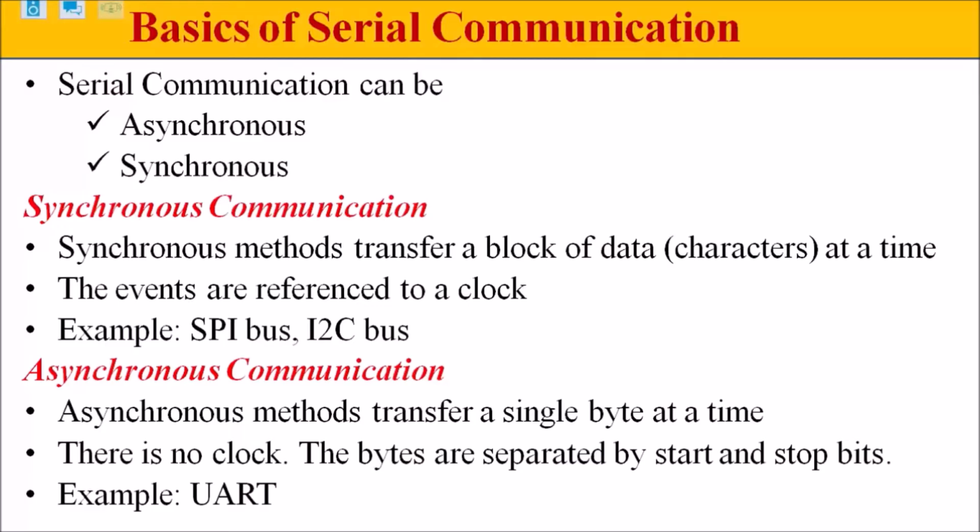So when the receiver receives a start bit, it will come to know that the transmitter is now going to transmit data. Or the receiver can synchronize its clock with the transmitter during that start bit. Different ways are there to pack this data into a frame.